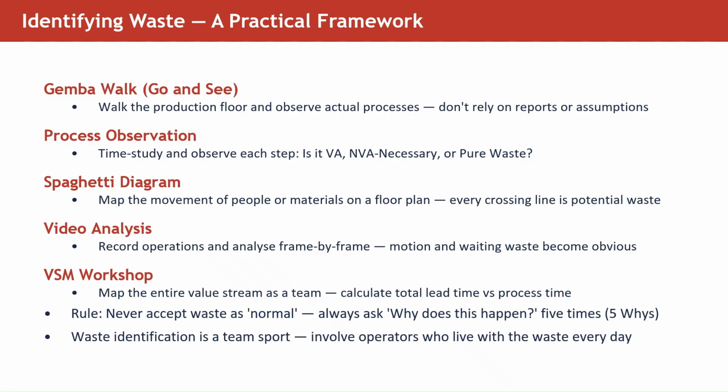Now, record the operation and analyze it frame by frame. Video analysis is again an incredibly powerful tool. Watch it back at half speed. Motion waste that seems invisible in real time becomes obvious on the video. And the most important, value stream mapping, the comprehensive tool that maps the entire workflow and calculates the value added ratio.